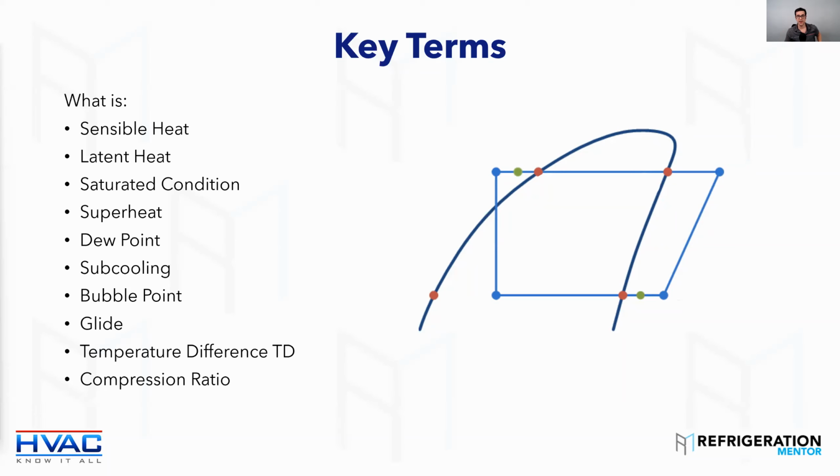And most compressors fail because of issues with compression ratio. And if you don't check that, you don't really know what's going on with the compressor. You can go to any compressor manufacturer, Copeland, Bitzer, Danfoss, Tecumseh. They will tell you, you need to understand that compression ratio. Too high a compression ratio, too high a discharge, is going to cause higher compression.